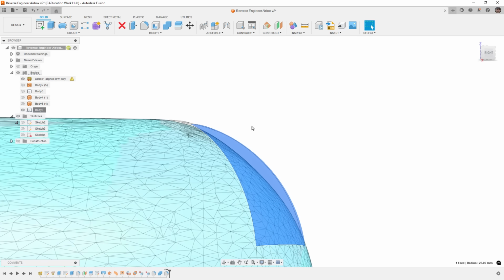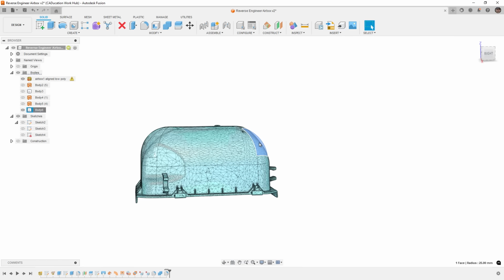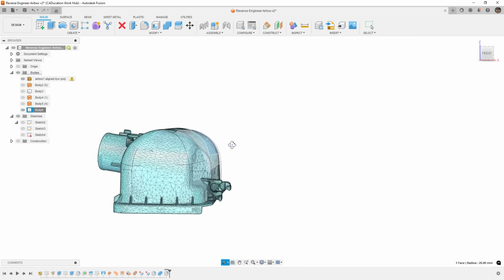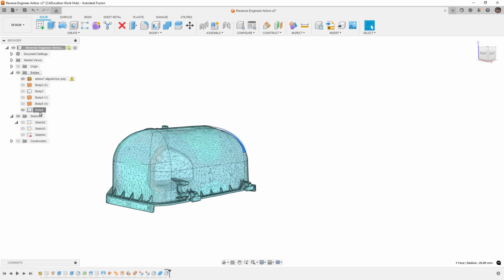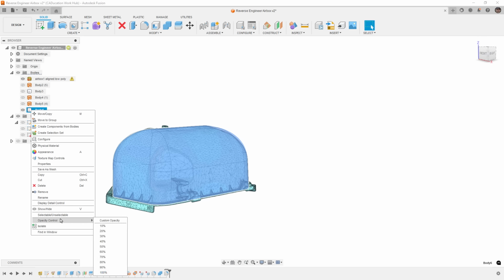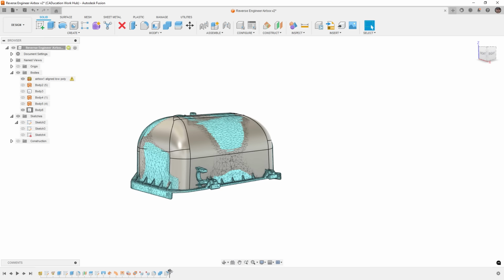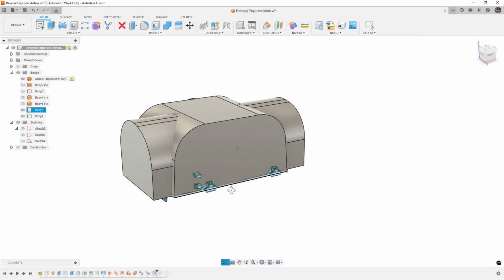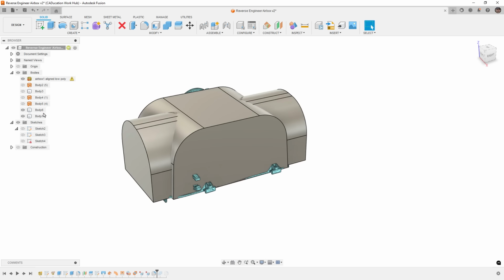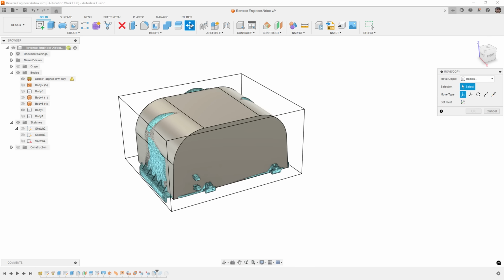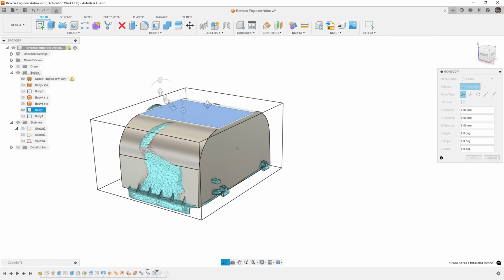So what this tells me is I potentially need to do a little bit more tweaking or messing around with those shapes. I'm going to show you a couple of tips that we can do for that, but I don't really want to spend a ton of time doing it. But what we can do is we can try to use tools like move face. We'll just change this to be faces. We're going to select this face from the front edge.